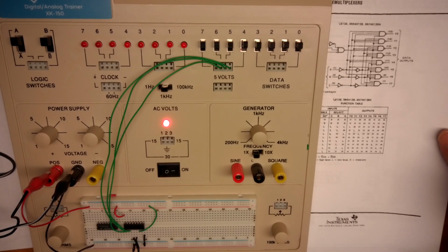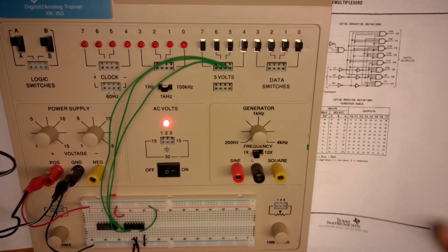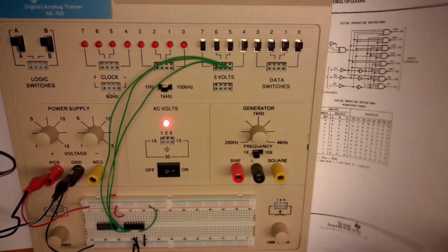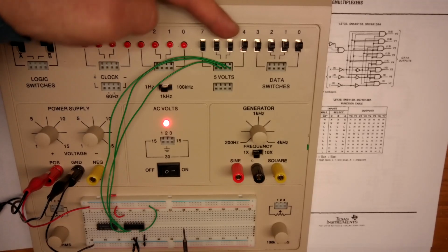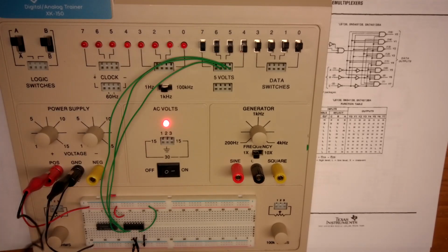Okay, now I am going to warn you of something. This may seem backwards to you. It is common that this one is active low. That means that the one I've selected is 0 and everything else is high. Let's go over and try 0. So that should set 0. This one should be a 1 now. We're going to find whichever one's 0, then we'll check on our pinout.